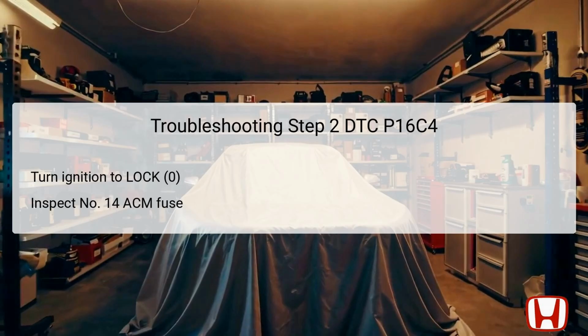Whereas if it is blown, immediate replacement must occur to rectify the power circuit issue. To gain access to essential components, the driver's dashboard lower cover must be carefully removed. This step is crucial for facilitating further inspection of the fuse, relay box, and the connections leading to the engine mount control unit. Once the cover is off, the next logical step is to disconnect both the driver's under-dash fuse